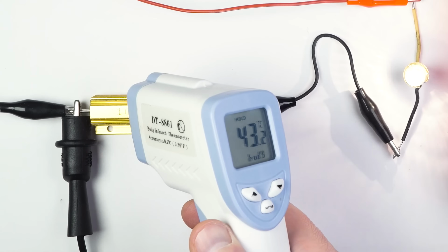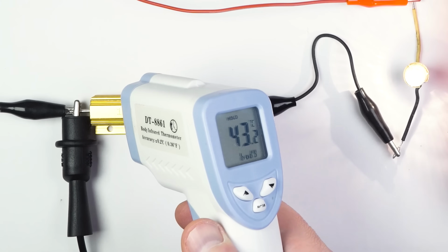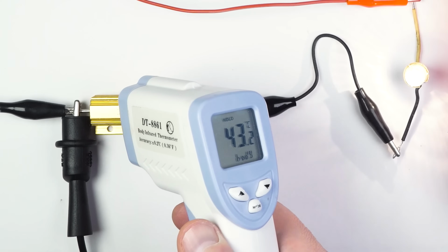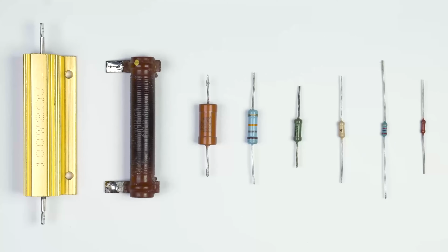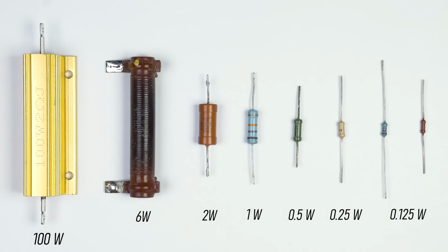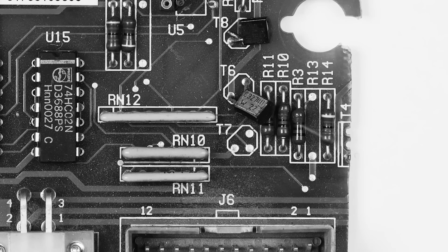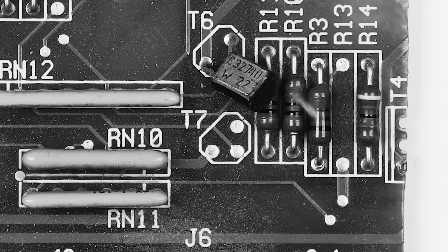At high current values, heating can be quite significant, so the resistor power rating is always chosen according to the load. As a rule, the higher the power rating, the larger the dimensions of the resistor. If you ignore the power rating requirements when building your circuit, your resistor may simply burn out and fail.